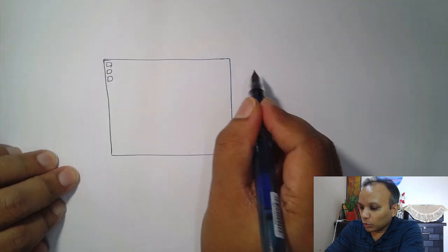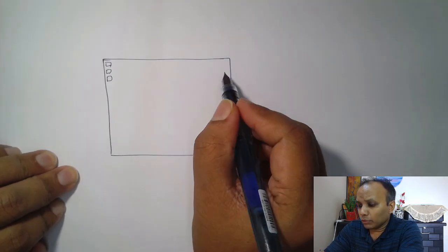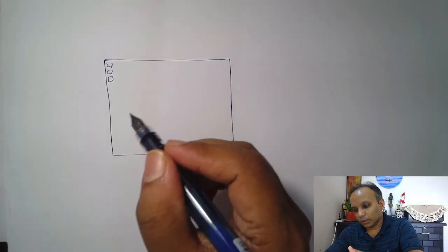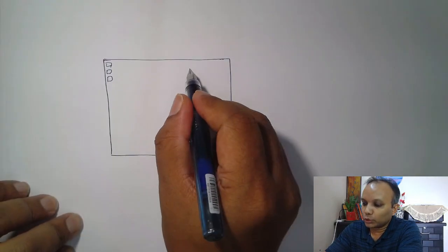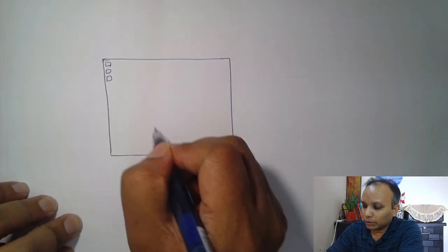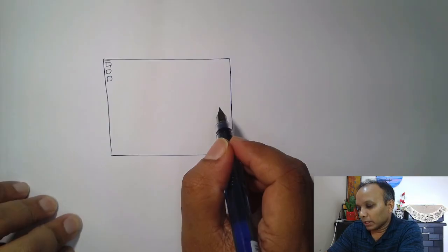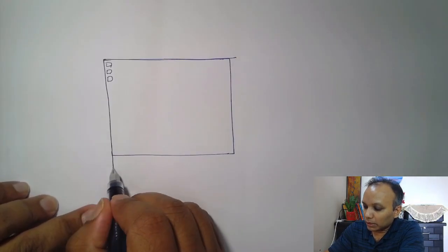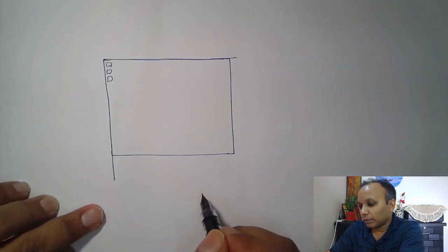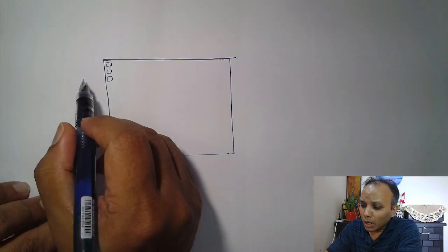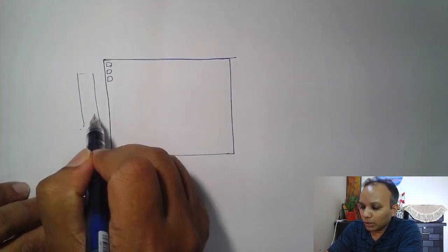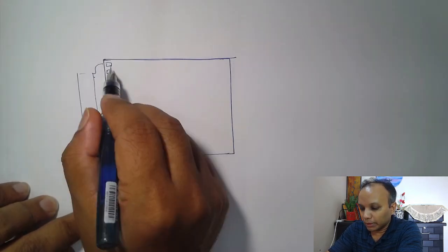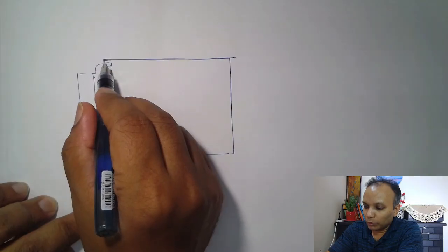Now, as you want to make this memory bigger and bigger, because you do need large memory to support large amount of data, so that you can store large amount of data, you can have reasonably big program, etc., to run all these things. Now, as you make your memory bigger and bigger, because of the physical constraints, because it will have its own dimensions and all, how do you access the memory? You will have some decoder which will basically enable some rows or some columns, basically where from you can read the data.